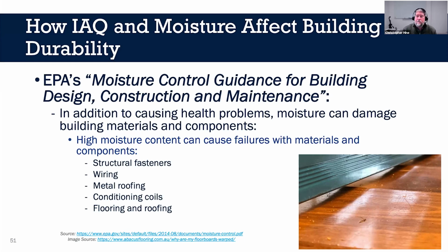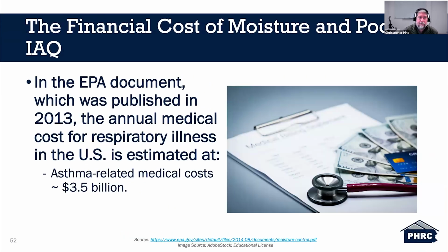Even though sometimes the home itself or the conditioned space above, the relative humidity might be at a point that's acceptable, the basement could have high relative humidity, which then goes through the subfloor and impacts the hardwood above. So there are many concerns for the building adversely affecting or being affected by high moisture content.